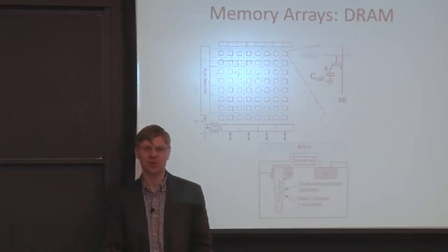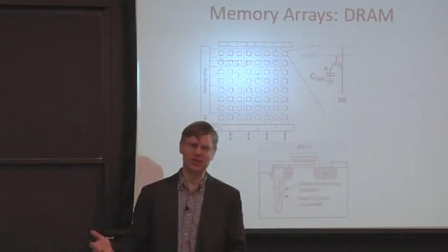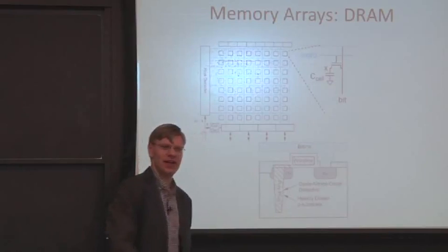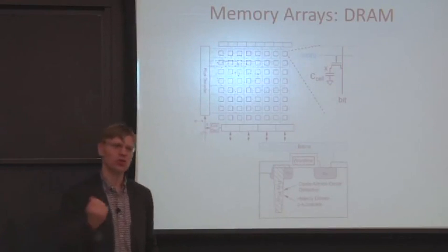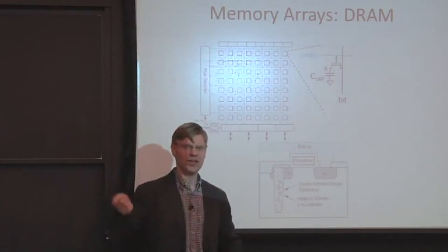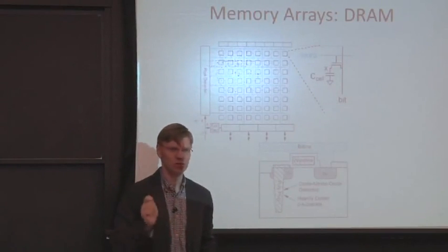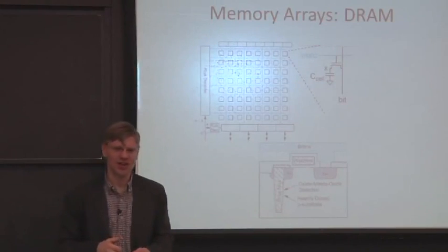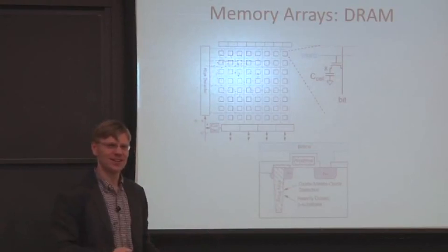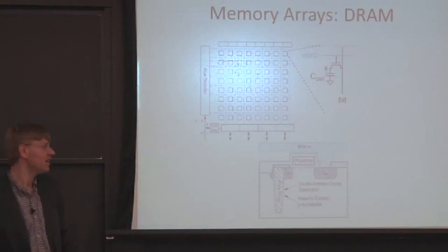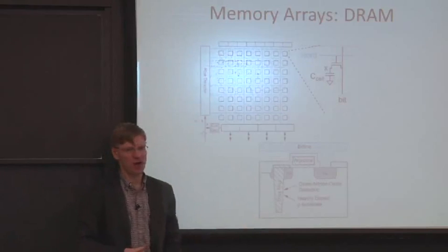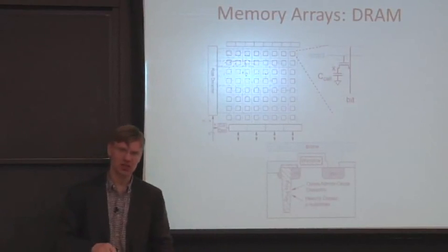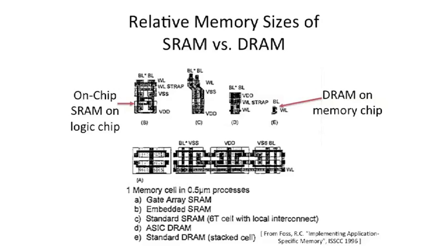Like there are some encryption attacks where people will effectively turn off a computer, then pull the RAM out and stick it in a different computer. And the DRAM will still hold the charge, still hold the information, even after you remove the power from it, because this is a bunch of little capacitors that will store that charge. That's a funny little case where DRAM ends up being a negative, but we're really doing this to have more space to store data, because each of these bit cells is a lot smaller.